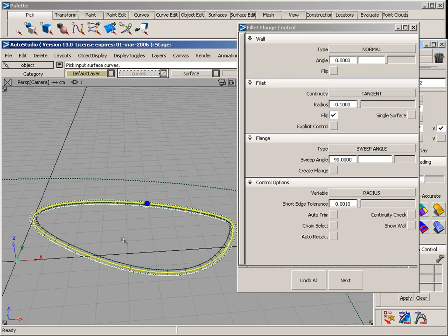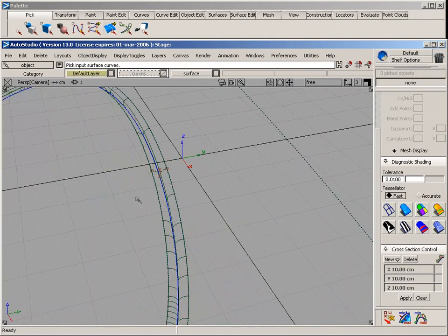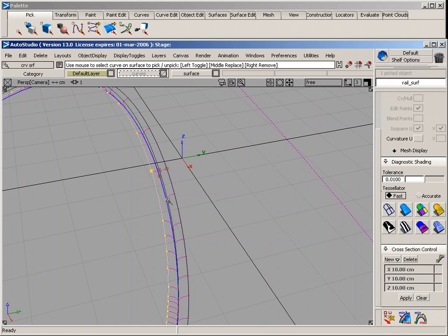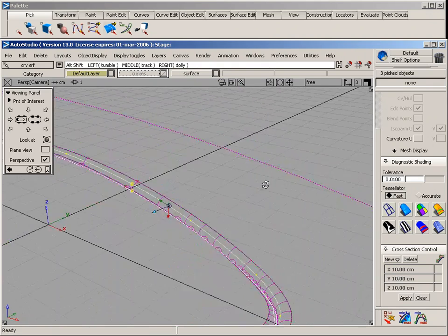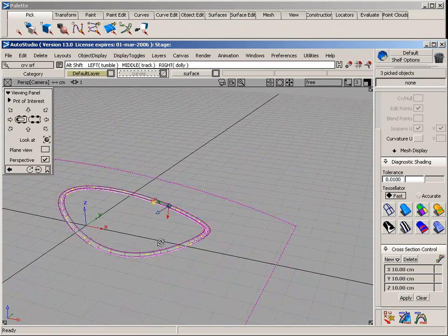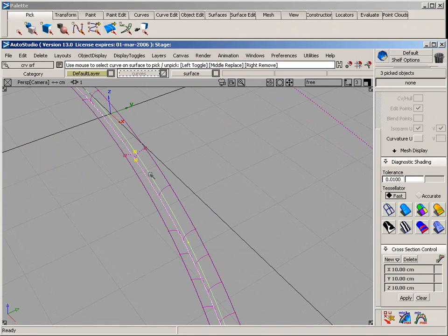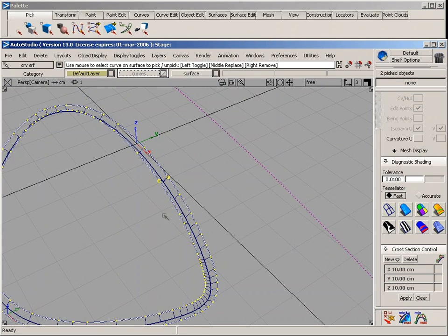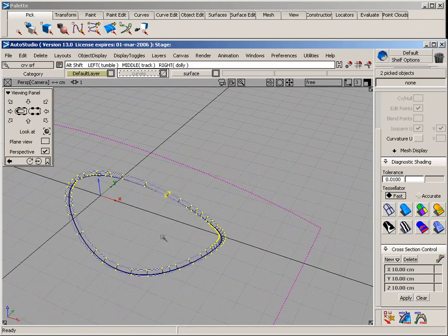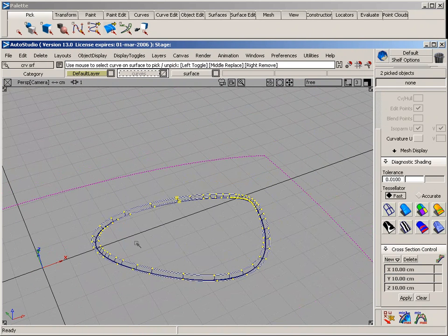Now the nice thing about this technique is that this automatically creates curves on surface. In other words, if you go to Pick COS, curves on surface, there should be one on this edge, and the original one that I created in the middle by projecting from above. So I'm going to start to delete the temporary ones that I used. So all that you're left with is, if you pick curves on surface, 2 here. This will allow you now to, for example, trim divide these 2 areas and thus create a nice part line.